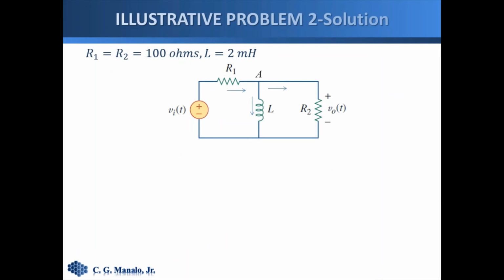Okay. So to solve the transfer function, we can use nodal analysis. So let's see, this is my ground here, and this is my node A here. I can perform a KCL on that node. So current entering equals current leaving. So this is current leaving, current leaving. Take note there that S equals j omega.